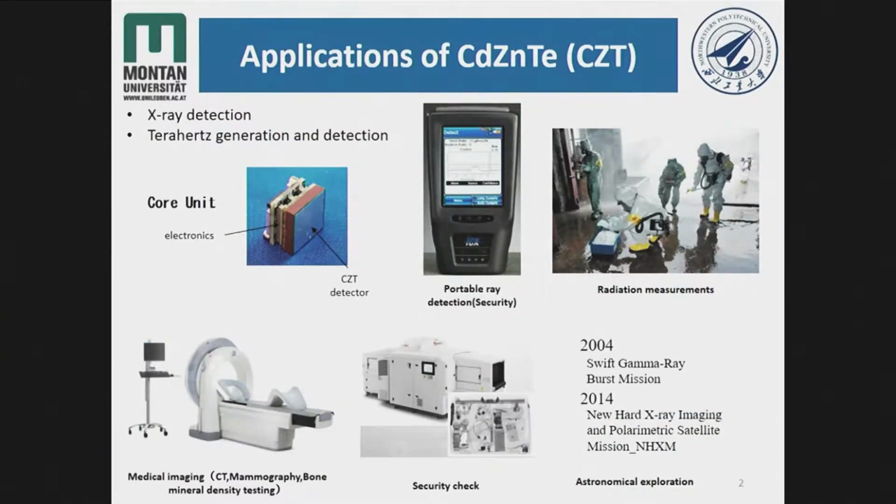First, radiation detection devices. They have, of course, many applications in today's society, probably also military applications. In principle, you want a perfect single crystal, for instance cadmium zinc telluride, which is a very prominent room temperature X-ray detection material, and you apply a very high voltage to this crystal, about 5,000 volts or maybe 10 kilovolts. Whenever an X-ray photon hits the detector crystal, you generate an electron-hole pair and you can detect it electrically. So this is about how such a detector unit might look.